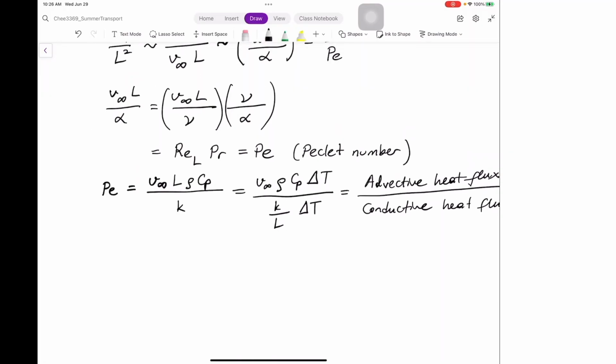So let's put a reminder here. Recall delta over L was in the same order of magnitude as Reynolds number L to the power -1/2, right? We did the scaling analysis, and we also have a particular solution for that, and we know the proportionality constant between them for approximation up to third order polynomial.